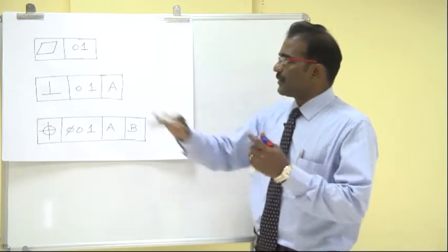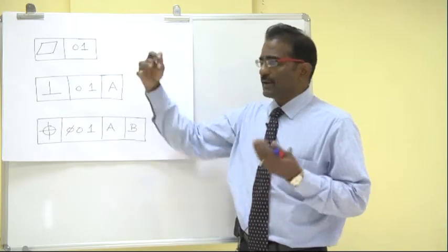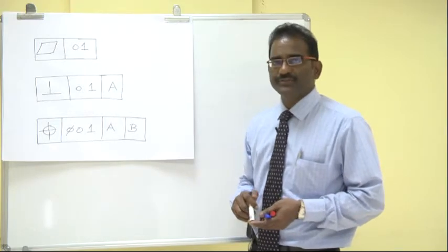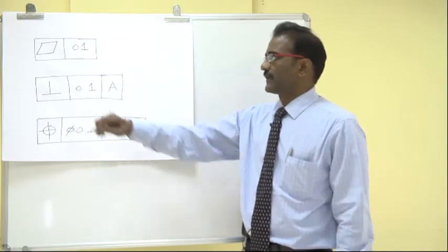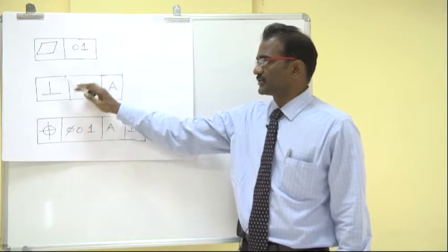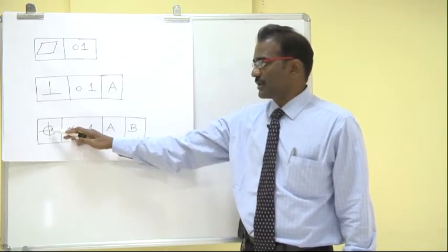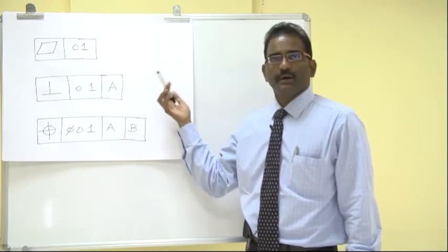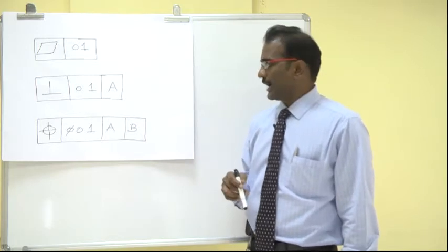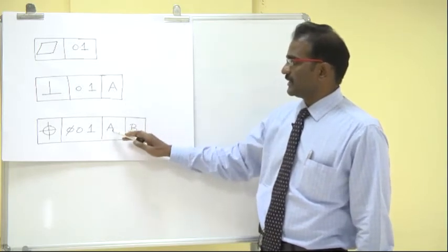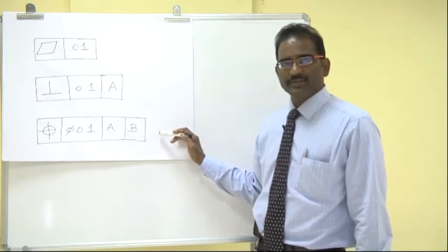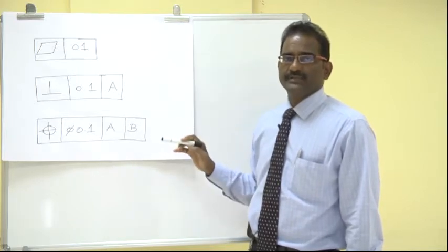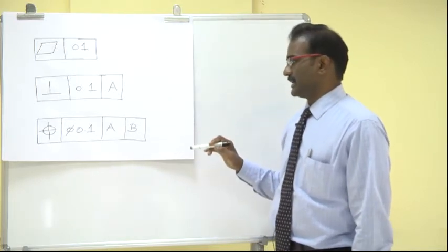So, depending upon the control and my application requirements, the feature control frame can have 2 boxes or 3 boxes or 4 boxes or 5 boxes, and again I repeat, if datums are mentioned, the order of the datums is extremely important.